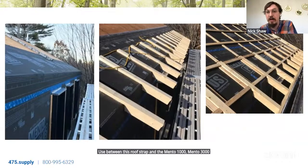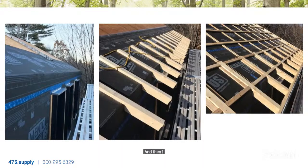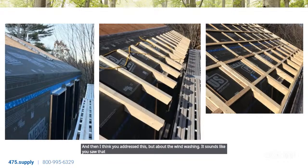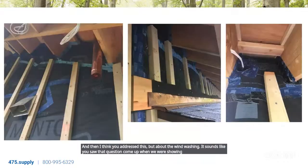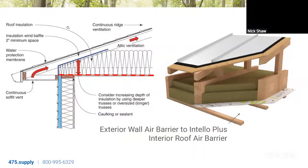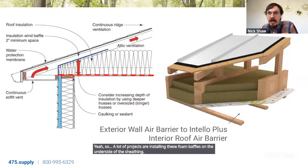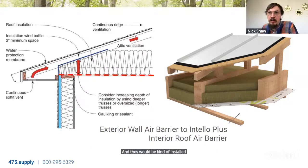And then I think you addressed this, but about the wind washing, it sounds like you saw that question come up when we're showing the two layers of insulation on this one. Yeah, so a lot of projects are installing these foam baffles on the underside of the sheathing, and they would be installed in between the truss system here on the underside of that sheathing.